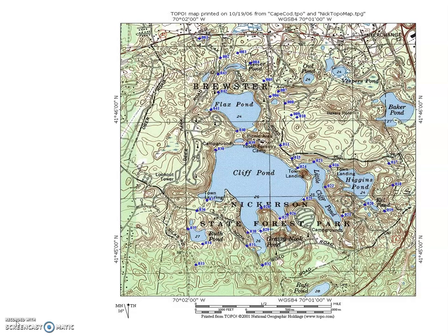So first of all, you need to look back at your table, and if, in this example, it is pumped at a rate of 0.8 million gallons per day, you need to read across the line that says 0.8 to look at the radius of the circle in miles.